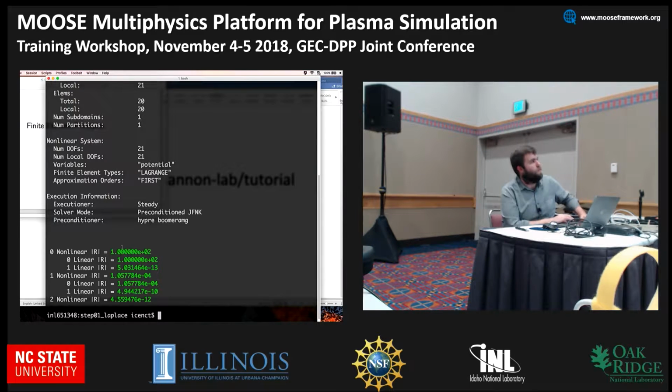So this is when you're putting in finite elements, when you're putting the strong form of your equation into a weak form. It's also called a residual form. So in the case of the example equation, you only have one term, so there's nothing to really move around. What Moose is trying to do is make the left-hand side of the equation get as close to 0 as possible, to minimize the residual.